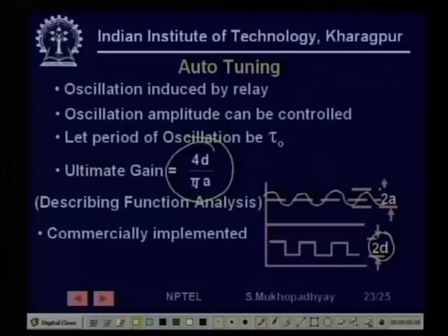So you are still finding that same gain PB star, but now using an experimental procedure which lets you set up an oscillation at one shot of a controllable amplitude. That is the big advantage, and then you can easily apply those formulae and get the gain.